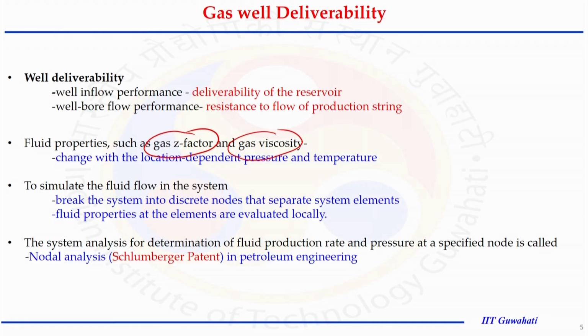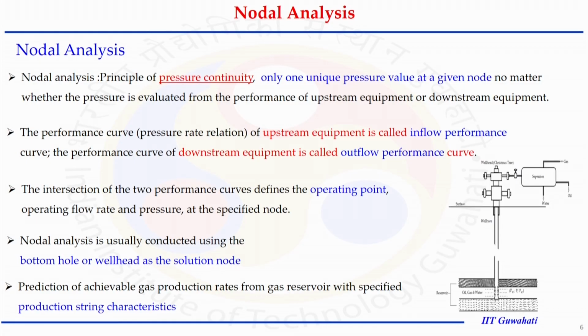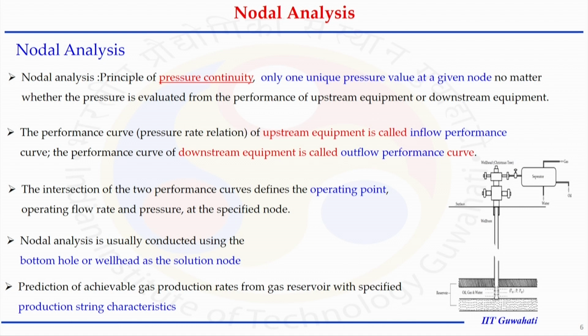In this lecture, we are going to understand the nodal analysis, which works on the principle of pressure continuity. For example, if we choose any particular point and we come to this point from right to left or left to right, the information is continuous. In our case the information is pressure. So at a particular point the pressure will be the same, no matter whether we come from this side or this side. This is the core concept of nodal analysis, called the continuity of pressure or pressure continuity.